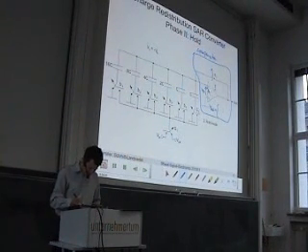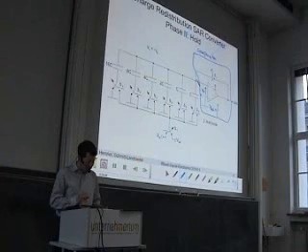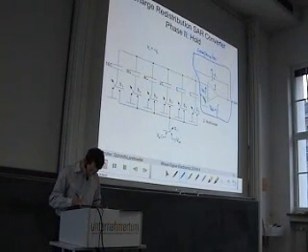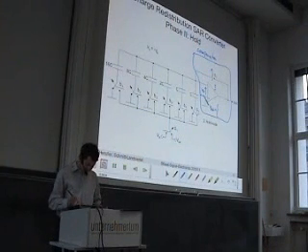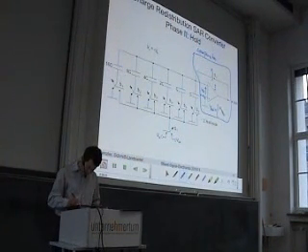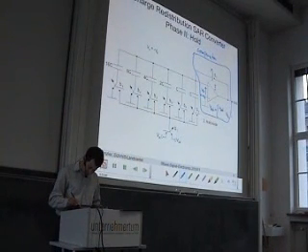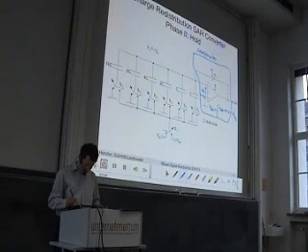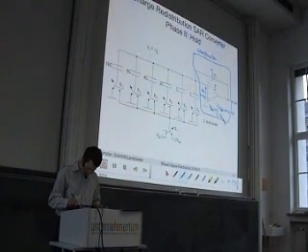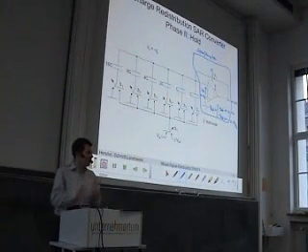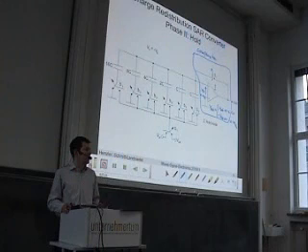And this Vd is equal to minus the voltage on this node, so minus the Vx. And this is Vsat if the Vx is less than 0, or it is minus Vsat if the Vx is larger than 0. So it works as a comparator. We can use this to compare against 0.